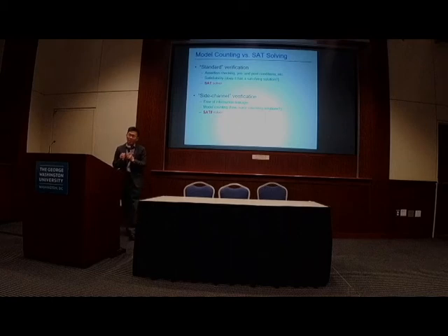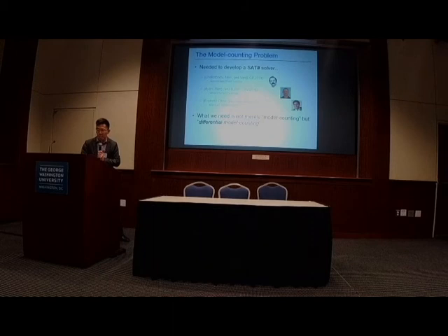Maybe this is only interesting to me, but for classic formal verification, where you, for example, try to do assertion checking or equivalence checking, there you typically would transform the problem into a satisfiability problem, where you use SAT solvers. But here, it's fundamentally different because you need model counting. You need to count the number of solutions for each Boolean formula.